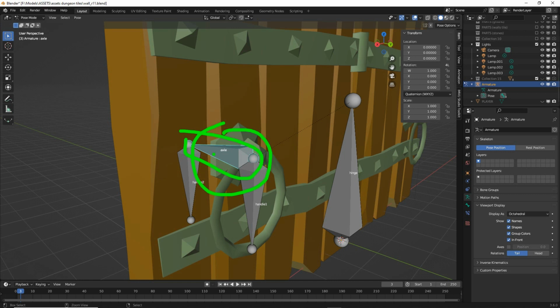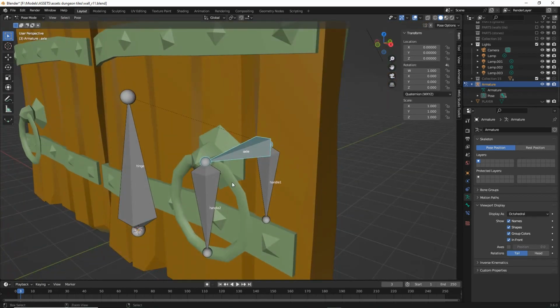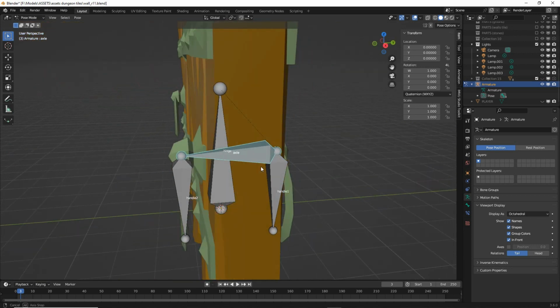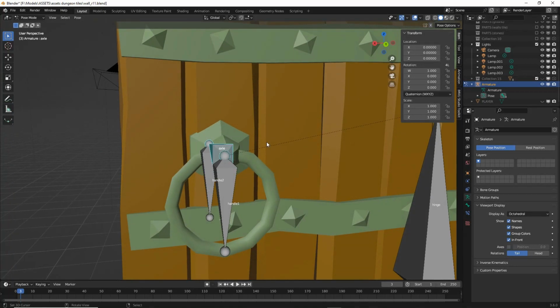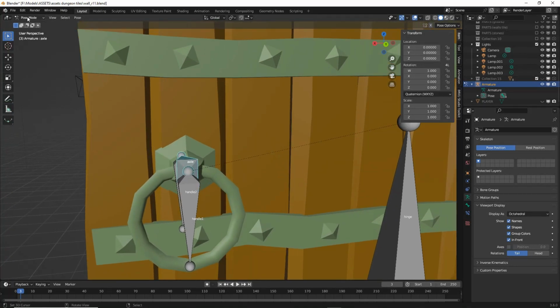If we can do it with one bone, just stick with one bone. Don't start adding bones to the armature just to try and compensate for something. If we can adjust the mesh to align with another section of the mesh that's being controlled by this one bone, if we can do that, do it. And it doesn't harm the mesh in any way.